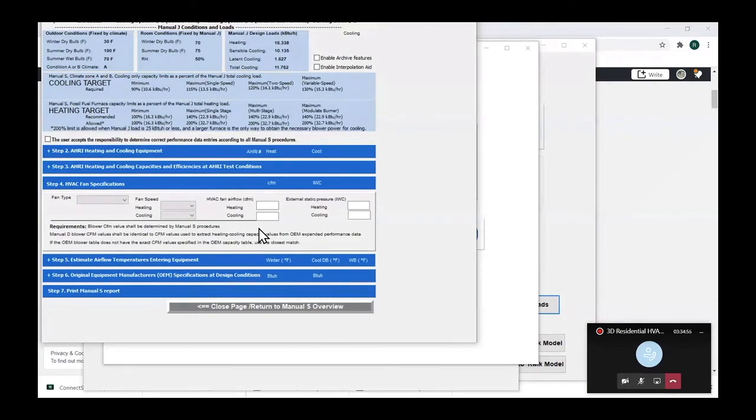And we just did our load counts. We're going to go back to Quick Model, and it's going to take those numbers with us back to Quick Model. And when we go into the Data tab, you'll see now in the room table, each room has a load, and each room has a target airflow. And we're going to use that to size the ducts. So that's a preview for tomorrow.